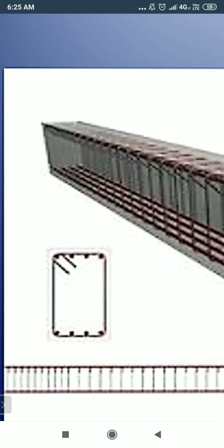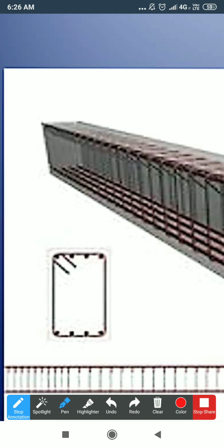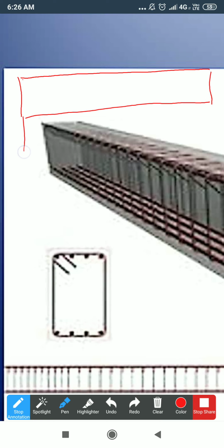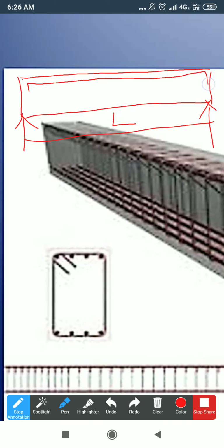In the longitudinal section, we represent the beam in the longer direction, imagining a span of L. For the given span length, we have to represent the reinforcement properly. In the top you can notice only one bar, but practically in three dimensions there will be four bars, and at the bottom also we represent only one bar.